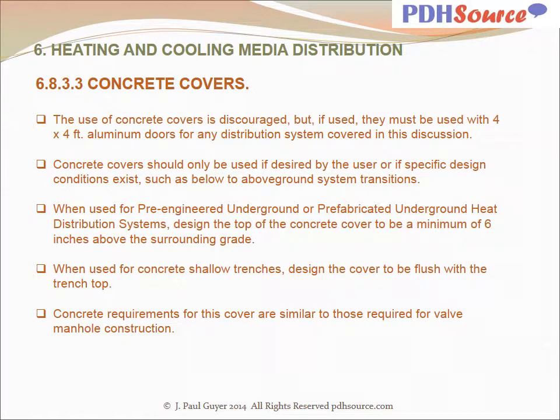With regard to concrete covers, the use of concrete covers is discouraged, but if used, they must be used with 4x4 aluminum doors for any distribution system covered in this discussion. Concrete covers should only be used if desired by the user or if specific design conditions exist, such as below to above ground system transitions.